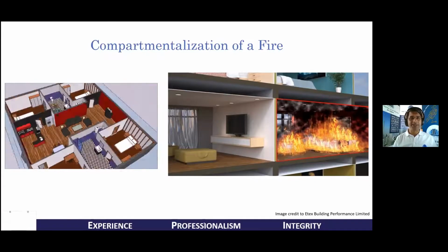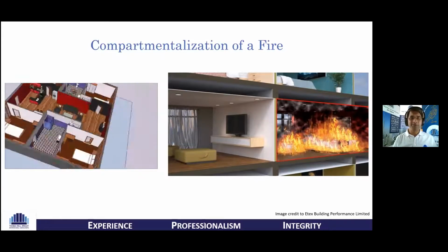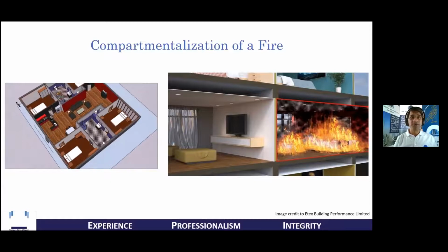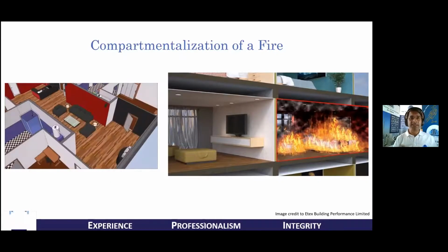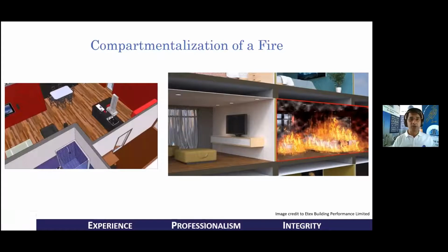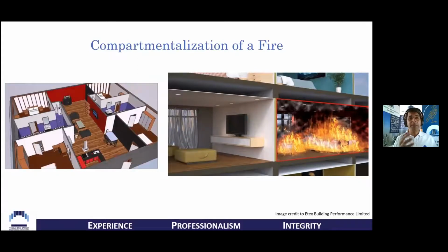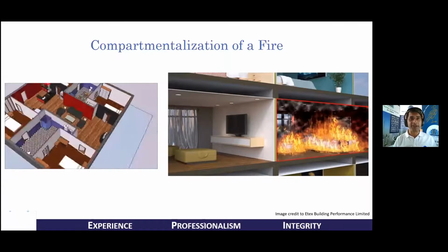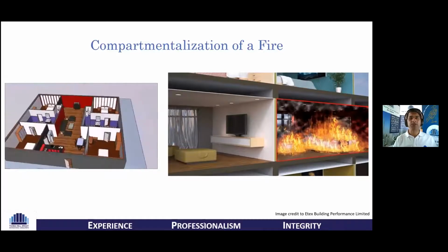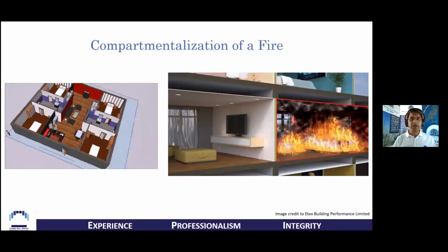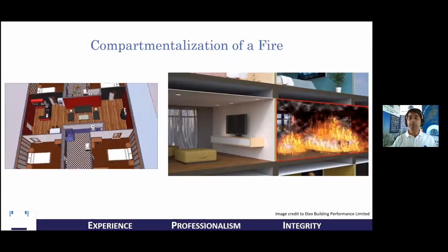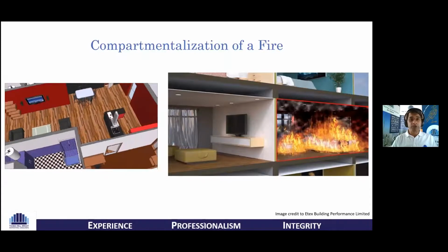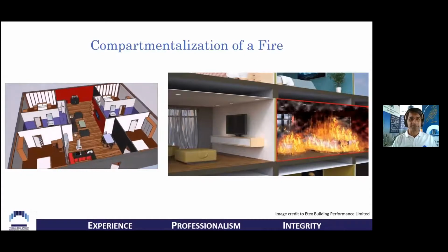We are looking at the concept of containment: the time for which the fire gets contained in a given room, floor, or section of the room is enough time for you to evacuate the whole building or the whole area, and enough time for the fire tenders to come in and take care of controlling the fire. Various jurisdictions, municipalities, as well as even tendencies of people in a given region affect the evolution of what is the right number.